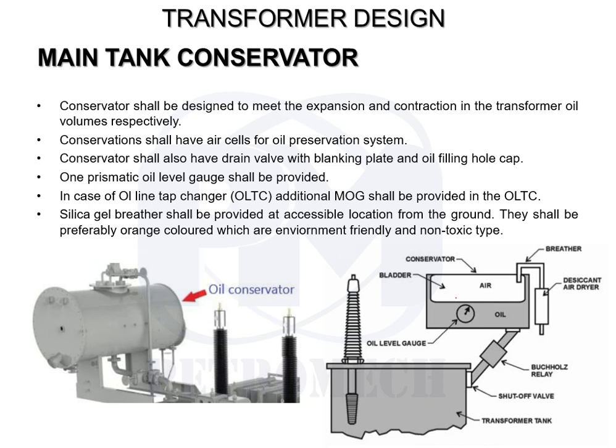Nowadays, preferably orange colored silica gels are used, which are environment friendly and non-toxic. So we do not go for the earlier used conventional blue type silica gel breathers. They are toxic and not environment friendly. Nowadays we go for this orange type silica gel.